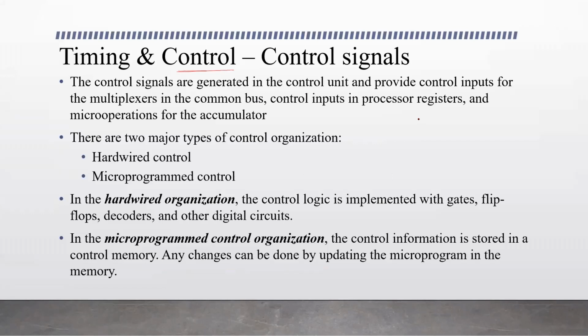We have seen the multiplexer inputs. The control inputs to the multiplexer are S2, S1, and S0 if there are three control inputs, or S1 and S0. These need to be controlled. These are controlled by the control unit, so these are all activated by the control unit. These are control signals. If it is register transfer, the value of this decides which particular register needs to be selected for transfer, or if it is some other operation that needs to be performed.